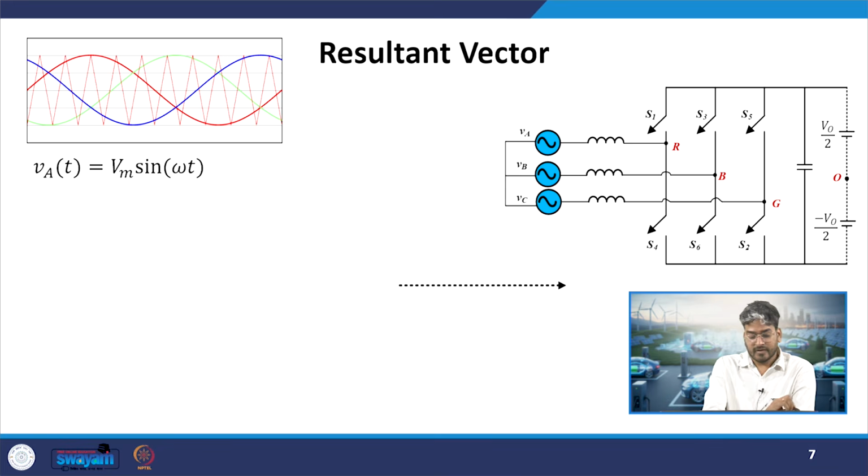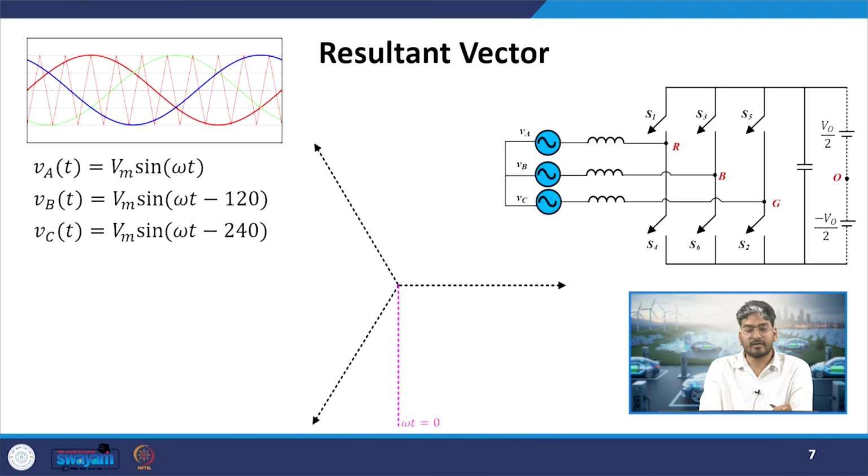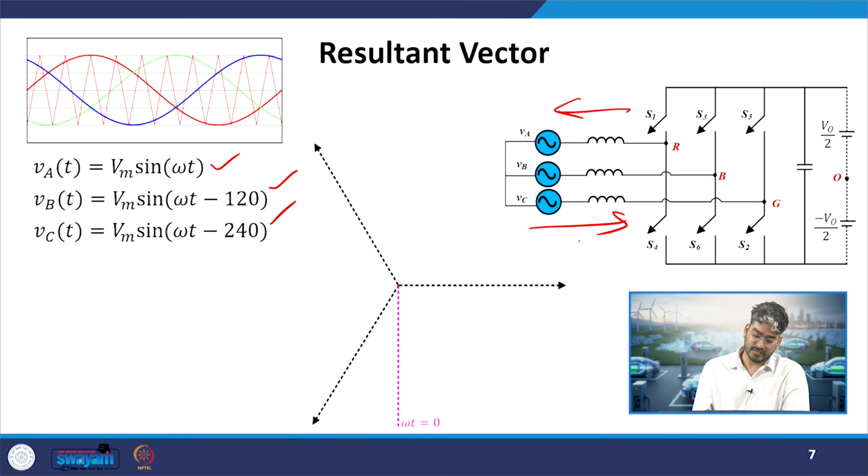Now we are discussing our closed loop control, where we have started our discussion on the projection theory, where we have seen that we have three quantities which are required to be controlled to decide our two factors, that is active and reactive power, which is exchanged by this converter. We have two control requirements, that is P and Q. They will be bidirectional, as this is an active converter, so I can control the active power flow as well as reactive power flow in both directions, that is it can be supplied to the grid or it can be absorbed from the grid.